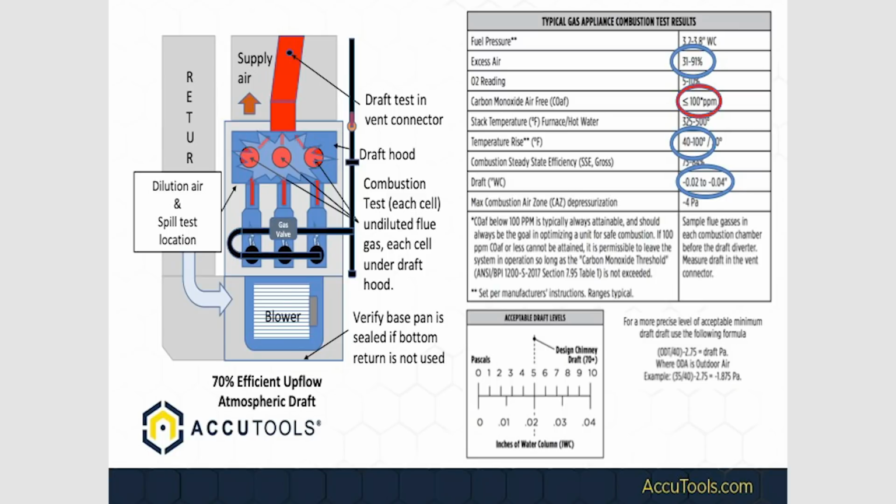They reused the existing venting system, right? 3-inch exhaust vent going out. Went from a single stage appliance to a 2-stage appliance. Well, Lennox furnaces on these required an exhaust accelerator, so they didn't put the exhaust accelerator on. And so now they got a furnace that's making carbon monoxide, and it's exhausting it outside, which was all good, except it's exhausting it underneath an overhang for a gas fireplace that's got a ventilated soffit. Because it didn't have the velocity to carry it out from the house, it pulled it back inside in the home through the ventilated soffit.